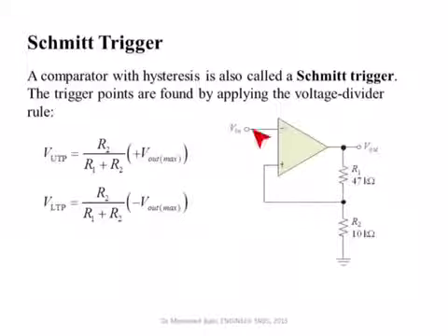Okay, so now the output will stay at its minus VCC value until Vn drops below this number. It follows exactly the same figure I've shown you earlier. So when Vn drops below minus VCC multiplied by R2 over R1 plus R2, then V plus will have a higher voltage than V minus, then V out will change to VCC again.